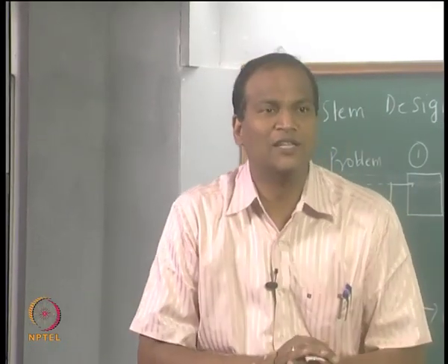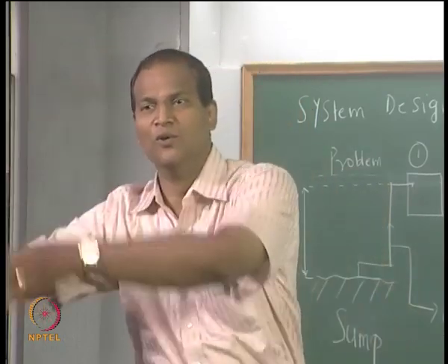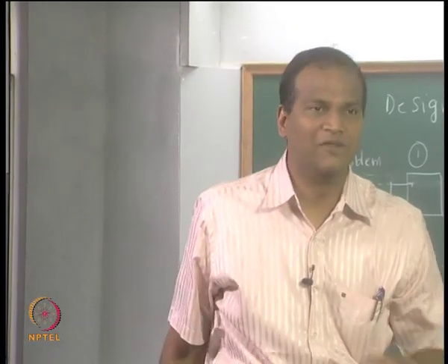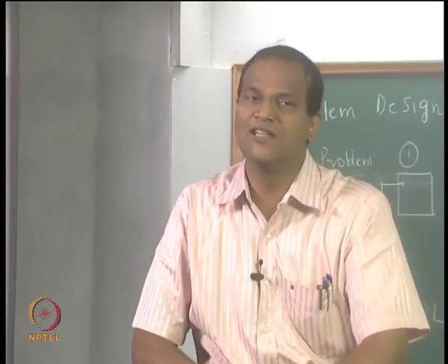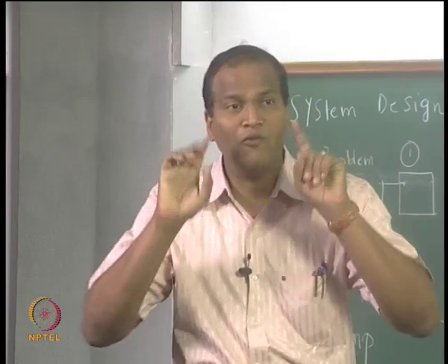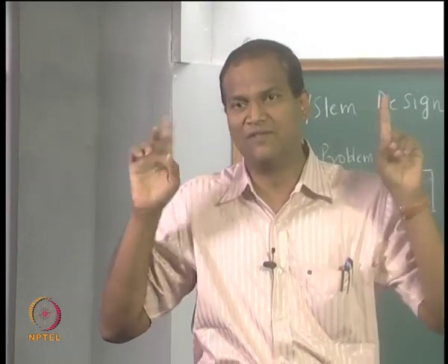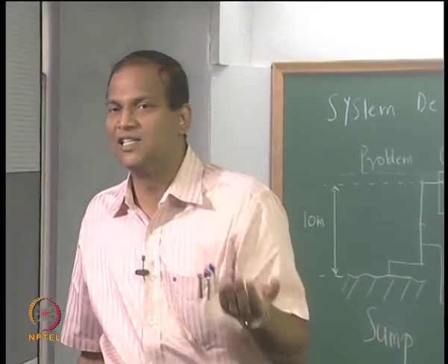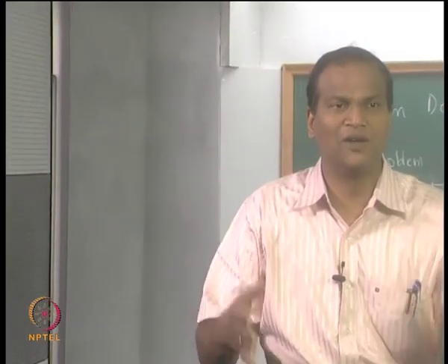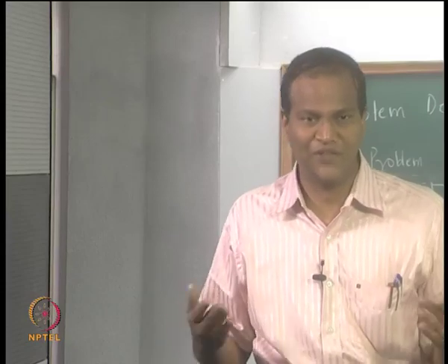If it is a 2 engine, they will not allow you to fly completely over the ocean for 8 hours or 9 hours. So even the 777, which is the latest, is subjected to the ETOPS standards, but a 4 engine jet, Boeing 747, the jumbo, is not subjected to that because it has got 4 engines. But now the twin engine itself is infinitely superior because it has got terrific fuel efficiency and so on.